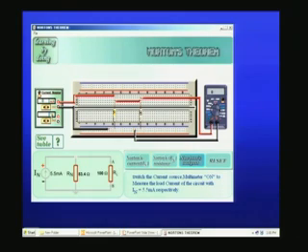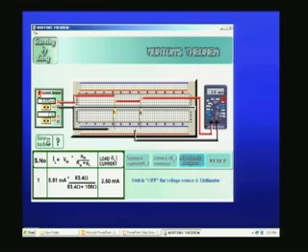Now I will switch on the current source and the multimeter, and if I connect here, I get 5.51 milliamperes as a source, and the series current measured is 2.5 milliampere, which is the value we obtained previously. The calculation can be seen on the screen: 5.51 multiplied by 83.4 divided by 83.4 plus 100 ohms gives me 2.5 milliamperes. That is what we got.